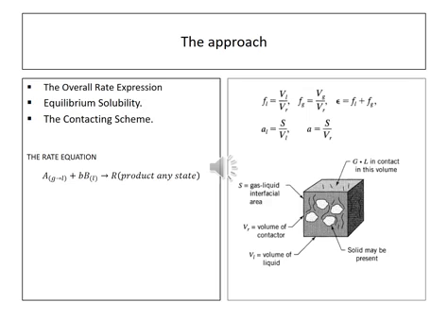There are some terms that you will come across that you need to be familiar with. One of them is the fraction of liquid in the reactor, FL, which is equal to VL over VR, where VL is the volume of the liquid and VR is the volume of the reactor. And we have the fraction of the gas, FG, which will be VG over VR.